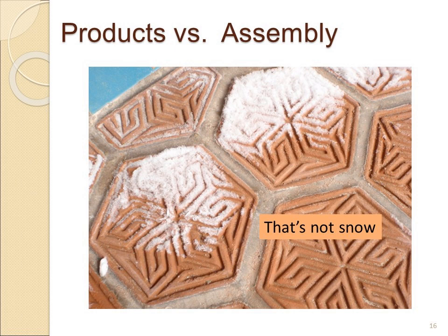But if that happens to an owner and you get an excessive amount of efflorescence on the top of the tile or through the tile, that also is considered a failure because now you have to go back and deal with the fact that it happened. And everyone blames the contractor, and you have to remove efflorescence in order to make the customer happy. And the problem also could be that efflorescence could continue or come back.